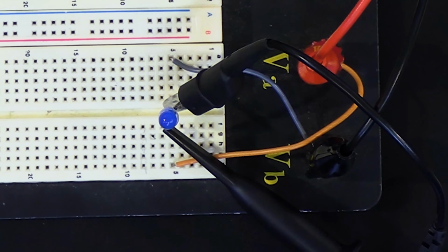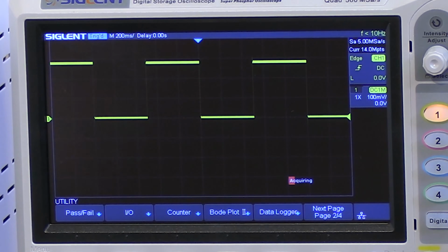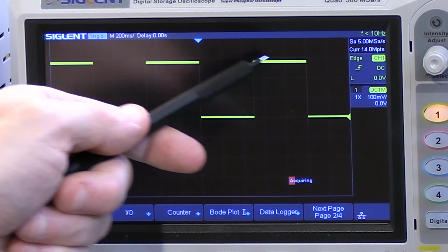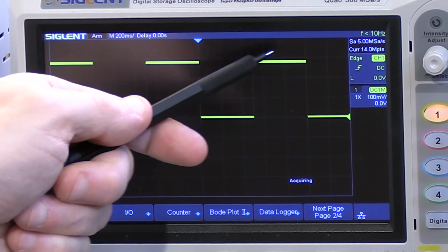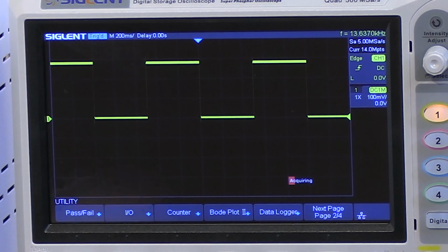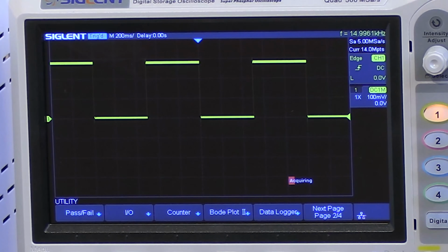We turn the output on and we see that this thing is now blinking, right? And we look on the top display and this oscilloscope is showing the voltage across this diode in real time. So this right here is the 0.0 volts. The top little hats up here are, I think I set it to 2 or 3 volts. Actually, I can read down here. It says 3 volts. So I'm driving at 3 volts, and then 0, and then up and then down, and then up and then down there. So it's turning on, off, on, off.